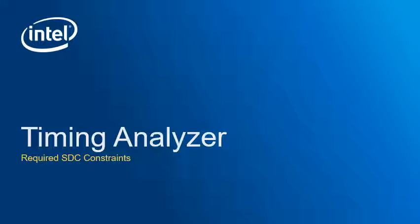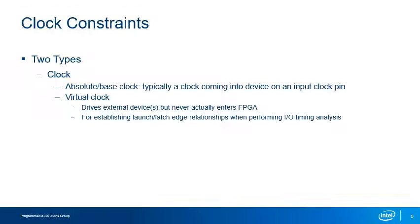To finish up this training, let's look at the constraints you'll need to fully constrain your design. The first and most important constraints you must create are clock constraints. Clocks in the Timing Analyzer are not actual physical locations in the design. They represent signal characteristics applied to a point in the design. There are two major types of clock constraints. The first type are absolute or base clocks. These are clocks that are typically input on the device's clock pins.